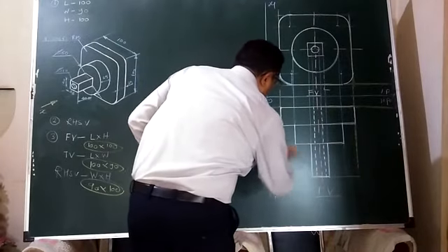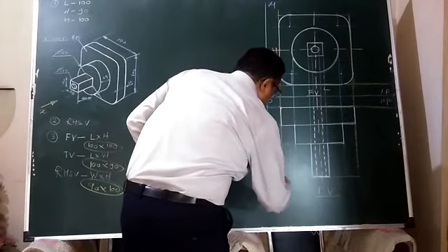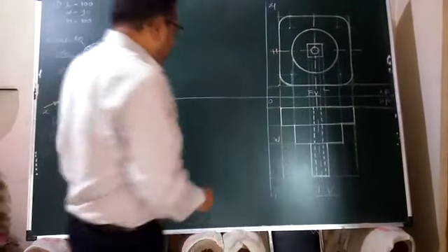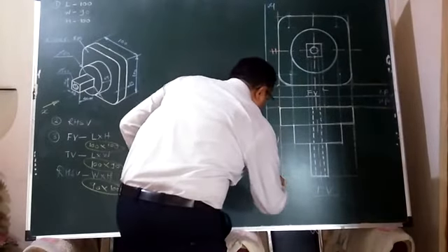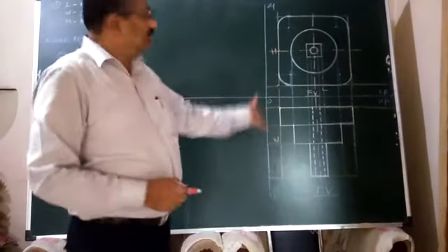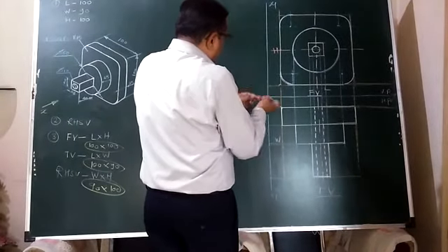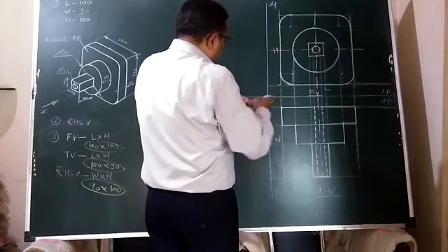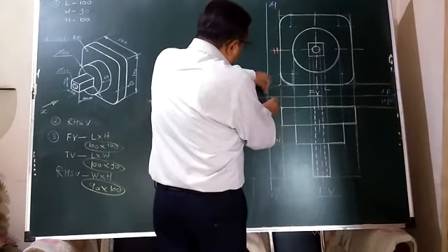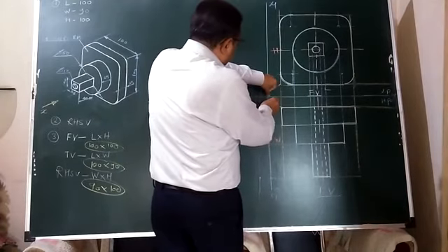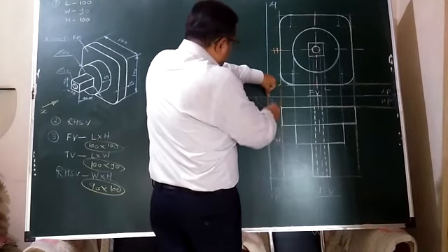First of all, from all the steps up to VRL, and now O is nothing but the point of intersection of both the reference lines, HRL and VRL. Now about O, you have to rotate those horizontally running projection lines from VRL up to HRL.